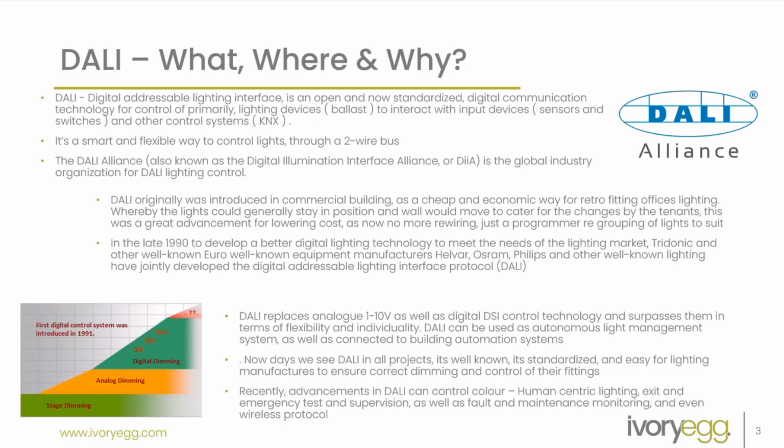So Dali was originally introduced in commercial buildings as a cheap and economical way to retrofit offices and lighting, whereby the lights could generally stay in position and the walls move around to cater for changes for tenants. This was a great advancement for lowering costs: no more rewiring, just programming and reprogramming of lights to suit. So just to dive into that a little bit, basically all the light fittings sit on a Dali bus.